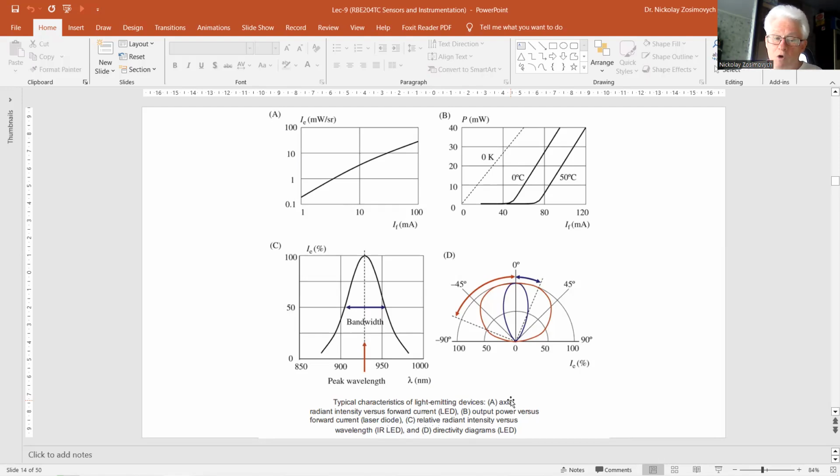Due to the short optical path the light travels in the device, some types of laser diodes contain an additional photodiode within the housing, suited to monitor and possibly control the output intensity.